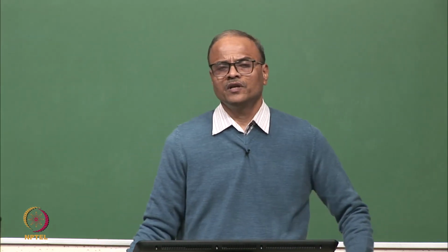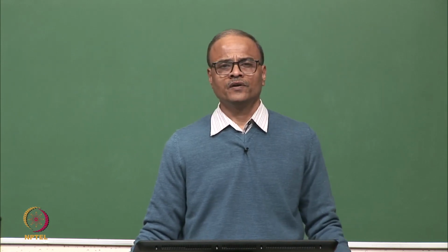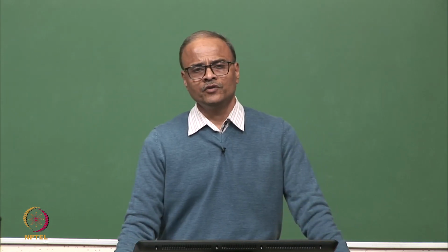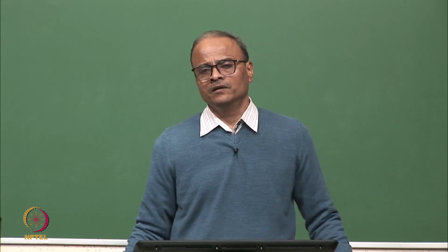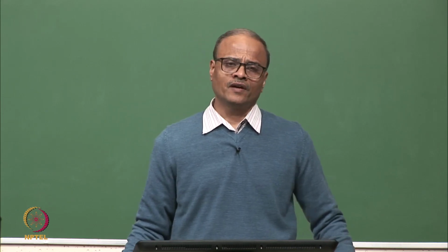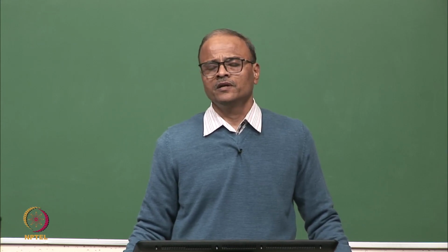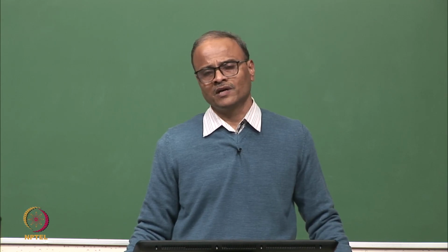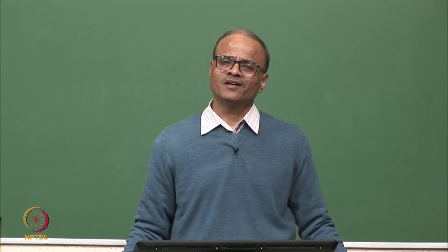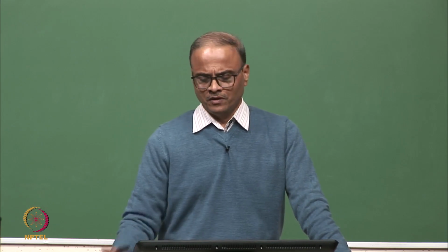A brief outline of the lecture is as follows. First, we are going to define different types of FRFs, and then we are going to look at how FRFs can be presented graphically. Then we will look at the FRF characteristics of a single degree of freedom system with viscous damping. And then we are going to also study the concept of stiffness lines and mass lines, and how to identify mass, stiffness and damping of a single degree of freedom system from the FRF.